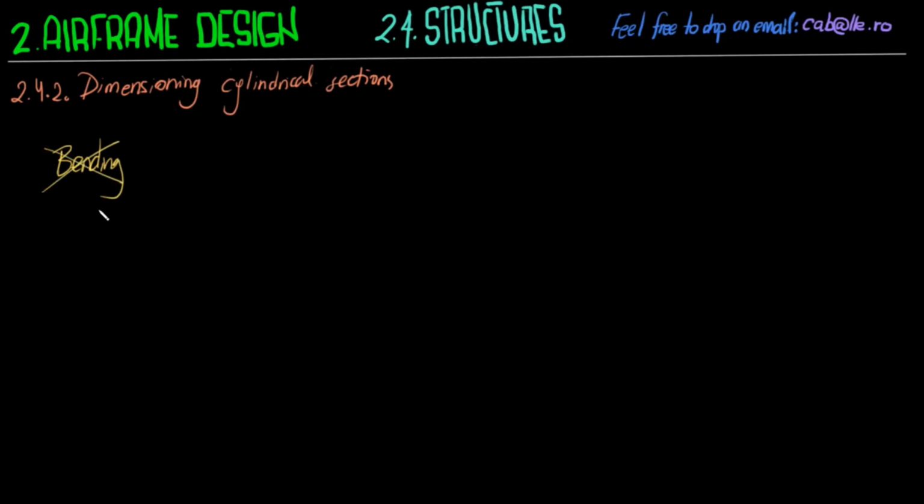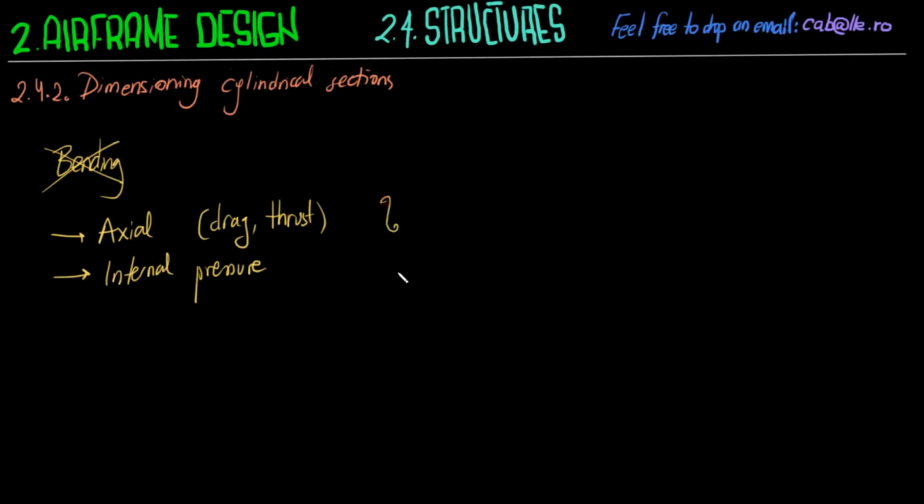Okay. So basically, the forces that a cylindrical section is going to withstand are going to be axial forces, which are axial drag and thrust, and internal pressure, in the case that the motor is firing, of course. So we're going to add these up.